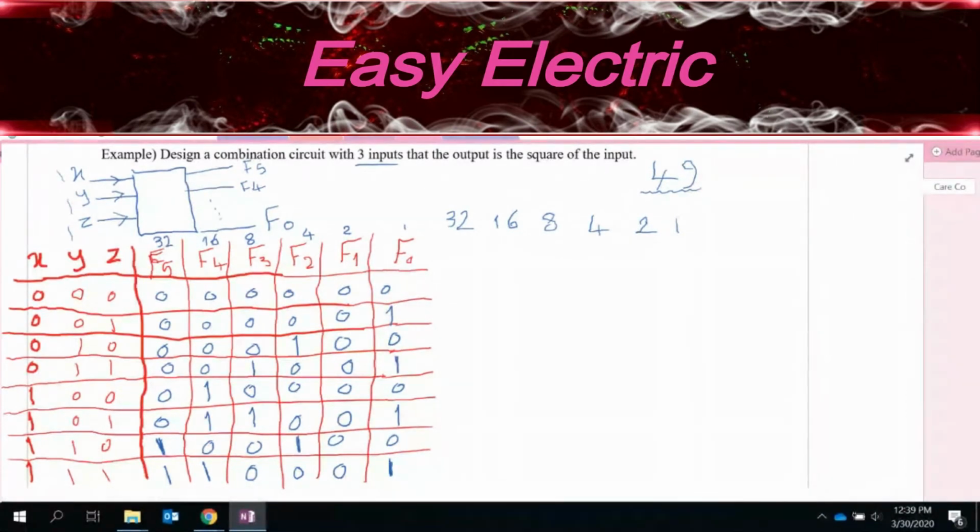Let me take a look at F0. You need to do the same thing for all of them because you have 6 outputs. You need to make 6 functions and have 6 K-maps, one for each. So start with F0. Again, I just write in the form of the sigma minterm. You tell me the numbers of the minterms. So what is the first minterm we have for F0?